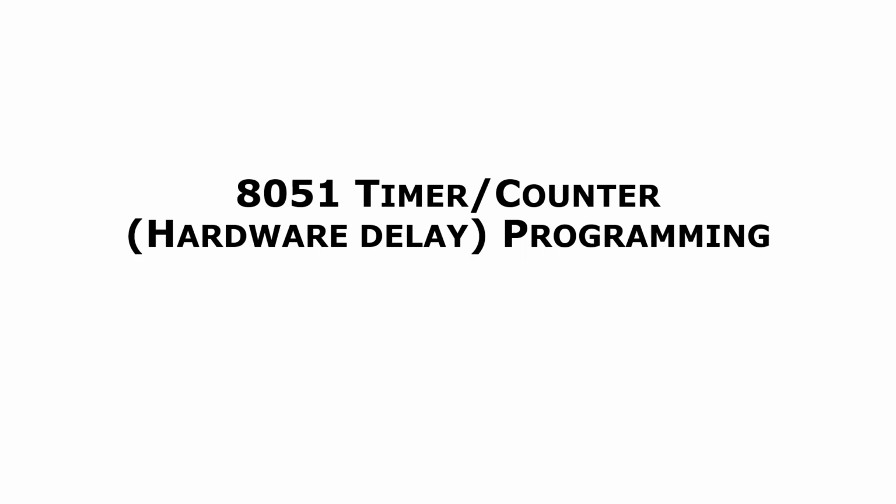One of the main advantages of using hardware delay is that the timer is generating the delay, and at that time, the processor is free to do other operations. But in the case of software delay, the processor itself runs the loop and creates the delay, which means the processor is busy. 8051 has two 16-bit timers, timer 0 and timer 1, that we discussed when we studied the timer.